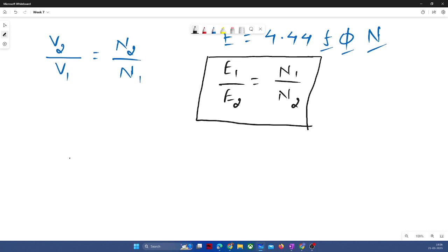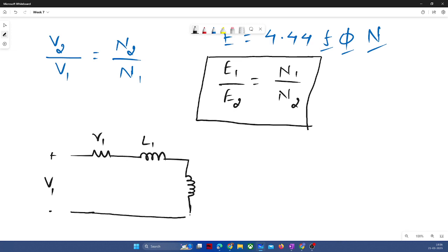So as we have given some supply in the primary side, with voltage amplitude of V1, there will be some primary wire resistance, so we can denote it with R1, and some inductance L1, and there will be some magnetizing inductance, right? Why magnetizing inductance? Could you explain that, anyone? What is the importance of magnetizing inductance?